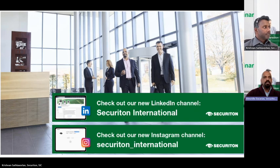And the next question is, can we set a delay for the ILIA beam to delay the alarm to the fire panel? Well, it should be noted that ILIA has an internal algorithm, and therefore a fire alarm will not occur immediately when the obstruction exceeds the sensitivity value. This will typically take 16 seconds to produce the signal. So a delay is not really required.